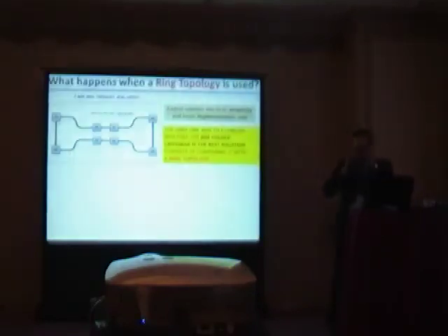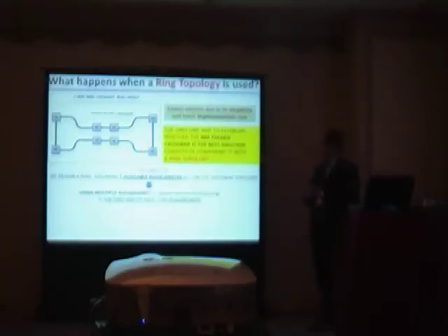So, since in our work we would like to find the best solution for our optical layer, we compare the 8x8 crossbar with a ring topology. As you well know, the ring topology is the easiest solution, because it is characterized by higher simplicity, lower implementation cost, and so on. In fact, in our work, we designed an optical ring by using 7 wavelengths, as in the crossbar. And notice that we use multiple waveguides by leveraging the spatial division multiplexing approach in order to satisfy all communication scenarios, processor-memory communication and inter-cluster communication.